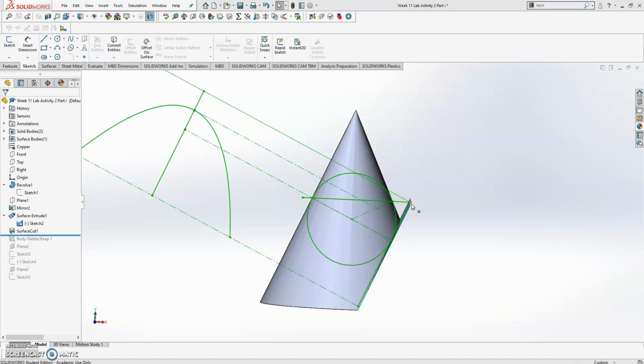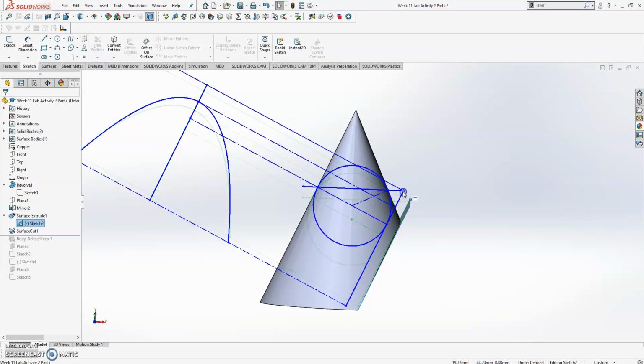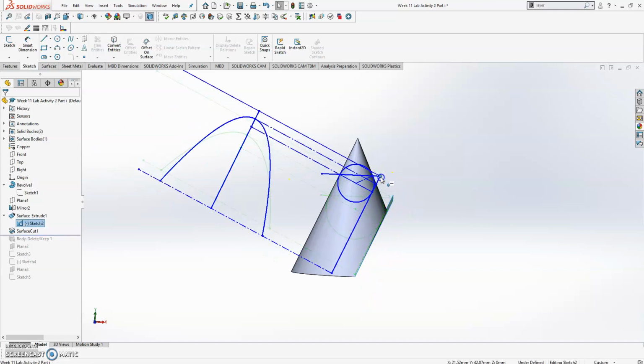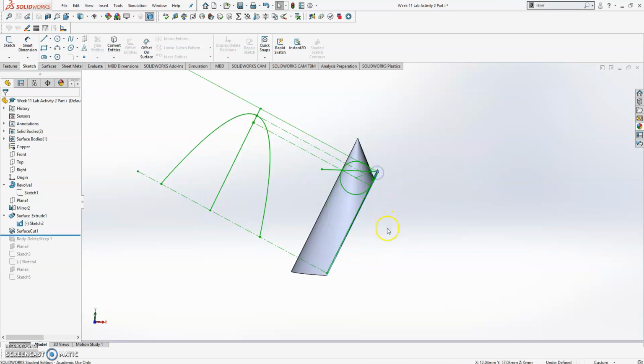And then once students have grasped and I've gone through each step of how it's built up, and the different relations between different parts, and what parts are parallel, and that the cutting plane is parallel to the edge view of the cone, and that the directrix is perpendicular to this cutting plane, I'll then be able to show how all these relations react and act together when the parabola is moved, and we can see the model changes as well.